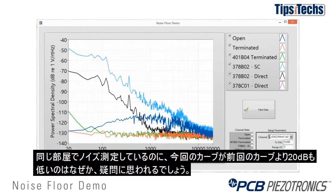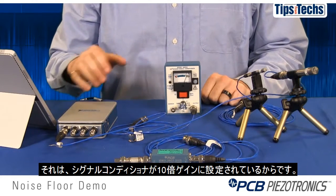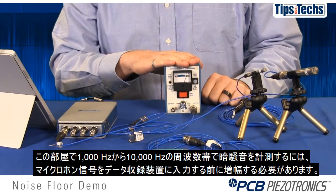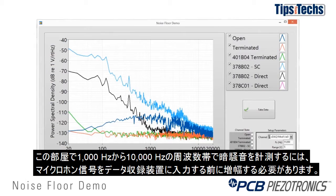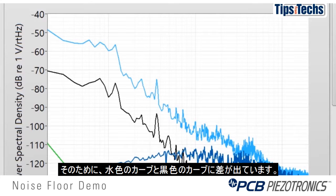And you may ask yourself, why is this curve 20 dB lower than the last curve, since we're measuring the noise in the same room? Well, the reason is that the signal conditioner was set to times 10 gain. And you can see why that may be important: if we want to make measurements of the background noise in this room in the 1,000 to 10,000 hertz range, we need to amplify the microphone signal before it gets into the data acquisition system. And that's what you see here between the light blue curve and the black curve.